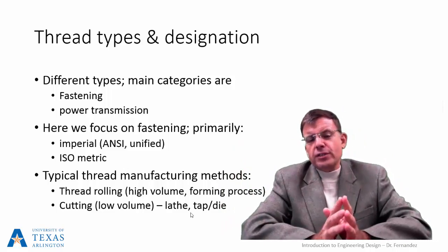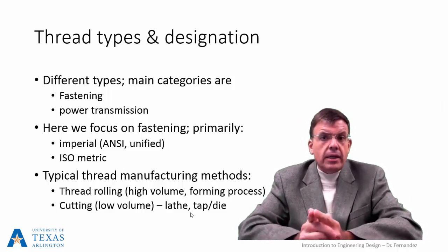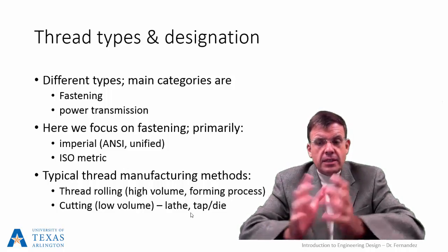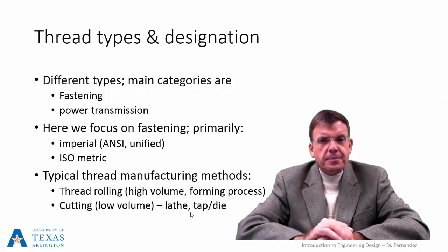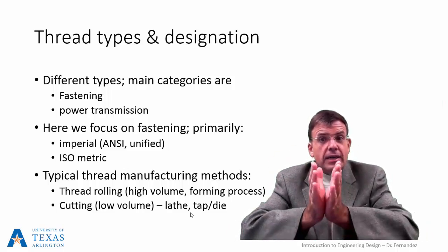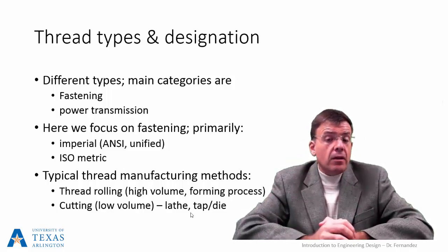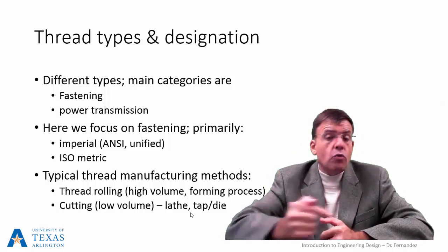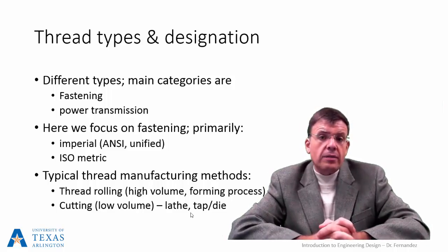Okay? And this is of interest to mention because this is exactly how threads would be generated in SolidWorks, and that's an exercise that's good to go through. You create a triangular cutting tool and then subject it to a helical path along which it would be doing an extruded cut, and that would result in a threaded body.